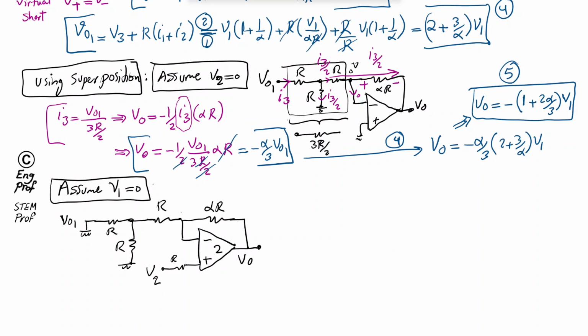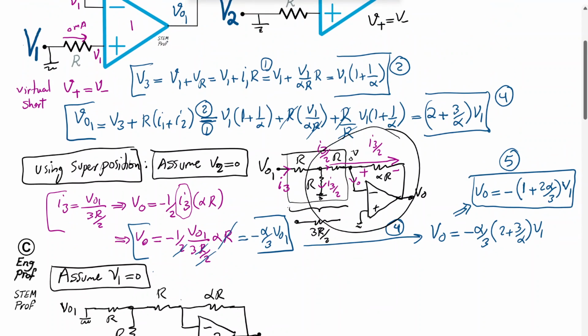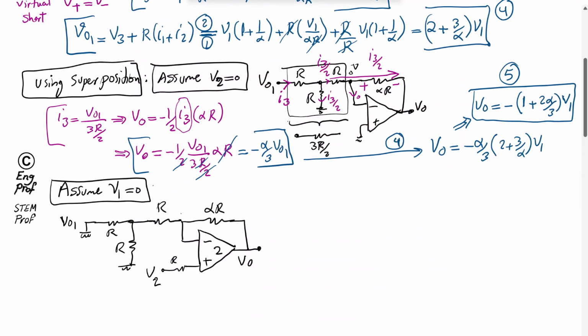Again, this is easy because this is exactly the look of a non-inverting amplifier, contrary to the previous one that looks like an inverting amplifier. So in the non-inverting amplifier, it becomes as simple as this. We have R parallel with R, so that would be R over 2. So the circuit effectively is equivalent to, say, R over 2 in series with R connected to the negative terminal,